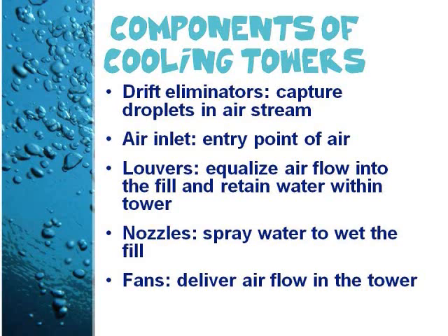Nozzles spray water to wet the fill. Uniform water distribution at the top of the fill is essential to achieve proper wetting of the entire fill surface. Nozzles can be fixed and spray in a round or square pattern, or they can be part of a rotating assembly as found in some circular cross-section towers.